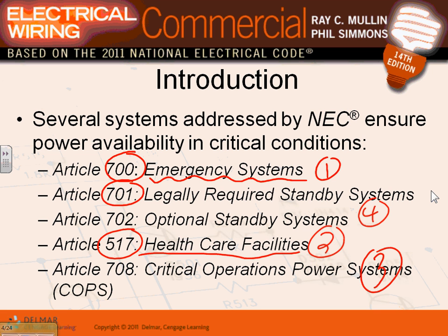No reason for it other than the continuity of the business, because we decided our business is good. We're not government, we're a private entity, and we decided our business continuity is important, so we need to back up. That's called optional standby system. Any questions about these four systems? Again, the most important system, the emergency system.